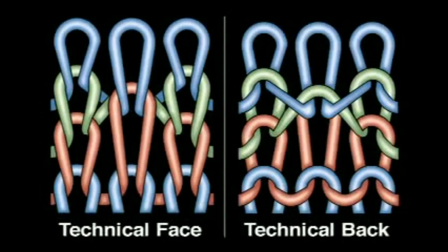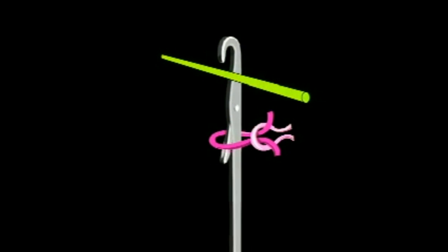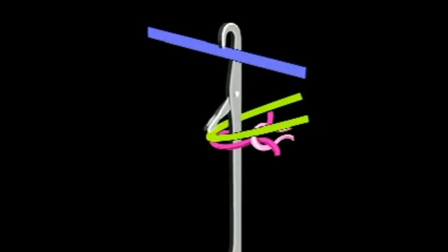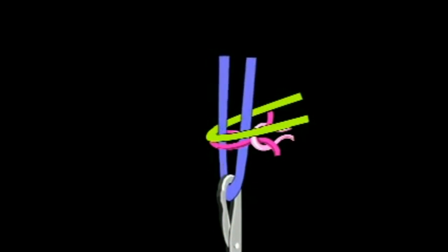How is a tuck stitch made? During the tuck cycle, at feed 1, the needle moves up from its rest position and the old stitch that has been formed is held and not allowed to clear the latch. Yet the needle moves up far enough to grab a second yarn, which is put into a tuck position. Both yarns are then kept at the rest position. The knit cycle occurs with the next feed of yarn. At this time, both yarns are cleared. A new yarn is fed and pulled through both the held and tuck loops, forming a tuck stitch.